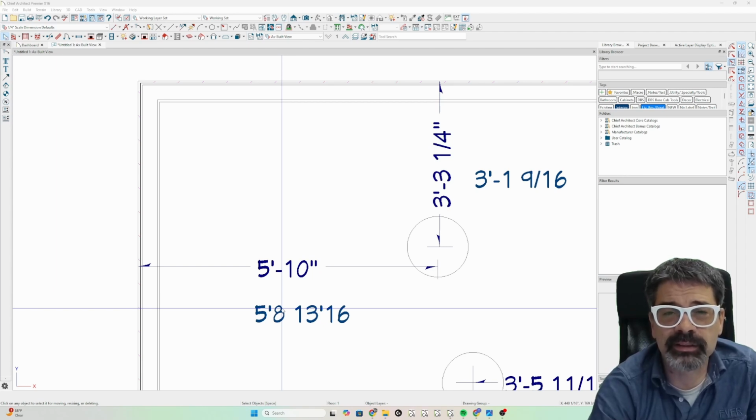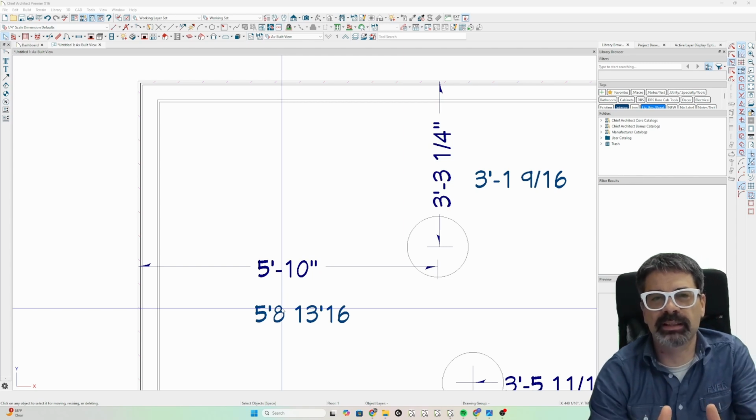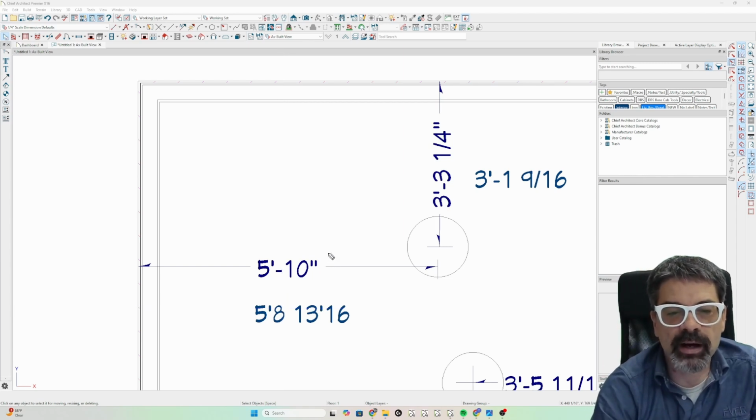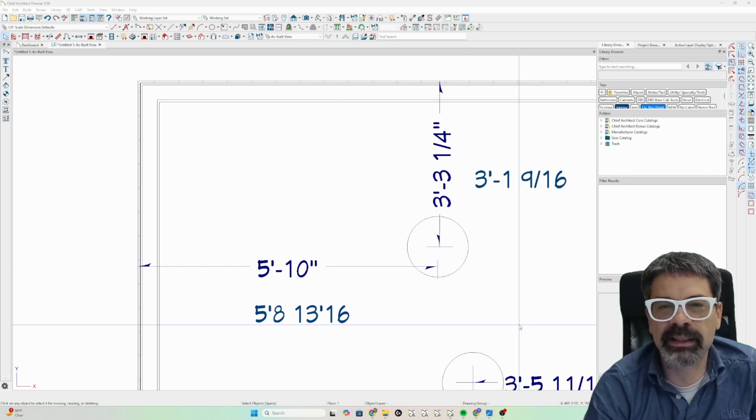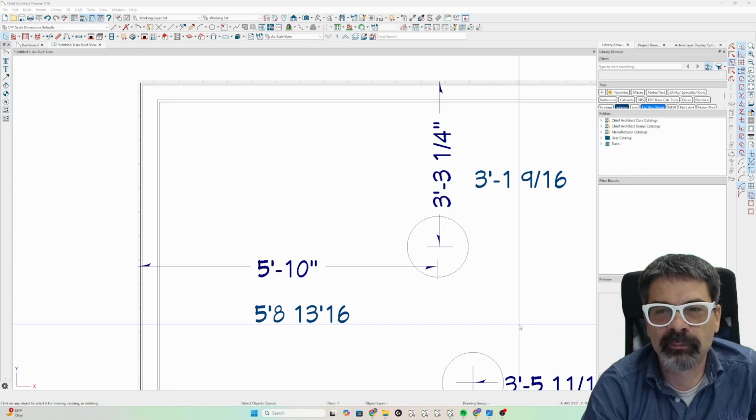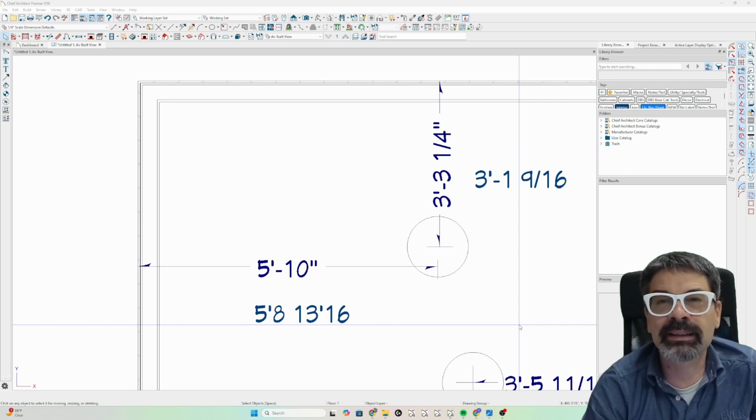We would have not been in the center if you had put that plumbing stack in, tried to get that plumbing stack in the center of a wall. You would have been off. Let me repeat this as loud as I can. And I hope a certain person on Facebook will listen, he knows who he is, and quit promoting the use of point-to-point dimensions. It leaves you and many other users that you're promoting this to great liability.